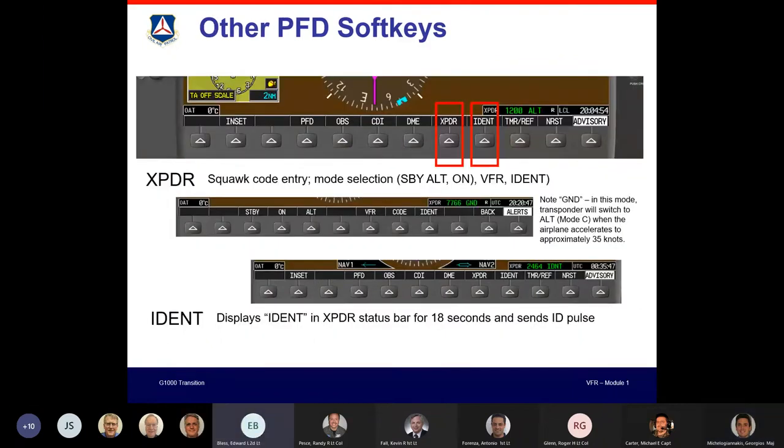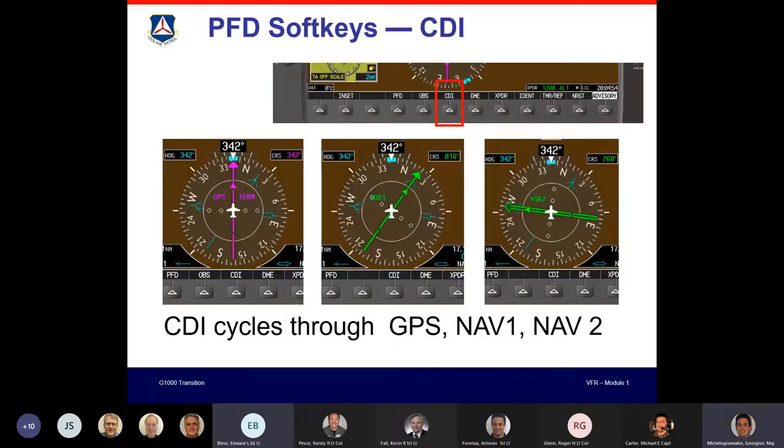Shayan, earlier in the demonstration, you said that if you establish a waypoint, that it can actually show you as a VOR on your screen. So are those VORs that we're looking at, are those real VOR stations, or are those also perhaps waypoints? So these RMI needles are derived from VORs. Yeah, real VORs. So when it comes to VOR1 and VOR2, basically nav1 and nav2, those are always VHF. So they're real VORs. Not to be confused with the OBS mode. These RMI needles have to do with nav1 and nav2, and those are VORs.